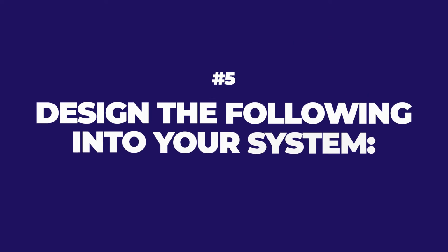Then number five, you will design these into your system. Number one, your general approach to safety on the project site. So you'll need to identify how are you going to approach it? Who's in charge of it? Hopefully everybody plus the superintendent. You don't delegate safety. But what is going to be your approach for training and orientation? What is going to be your approach for monitoring? And most specifically, what is going to be your approach for correcting the deviations from that safety plan?